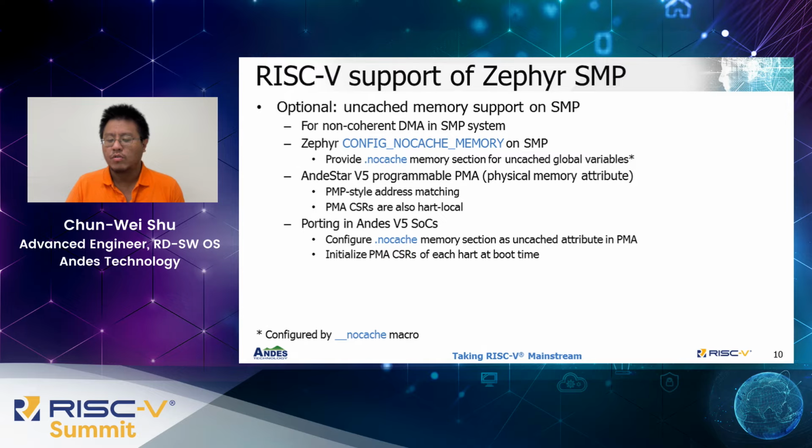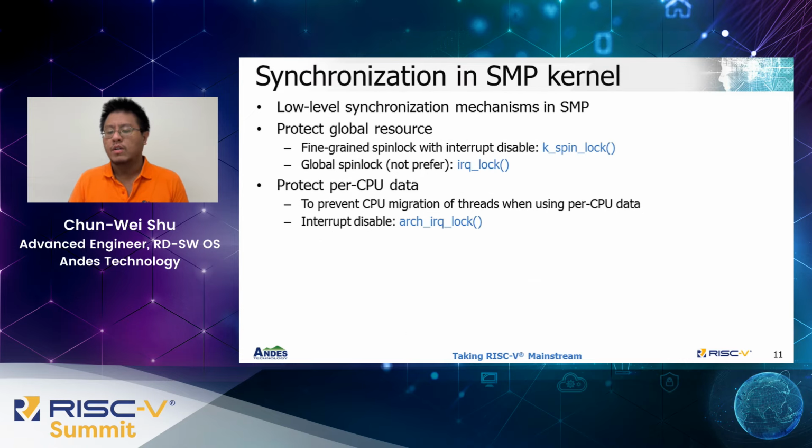Our PMA will use PMP-style address matching, and its CSRs are hart-local. So, to support it on SMP, we will initialize the PMA CSRs of each hart at boot time in the Andes platform. Then, I will talk about the SMP synchronization concept we use in the architecture porting.